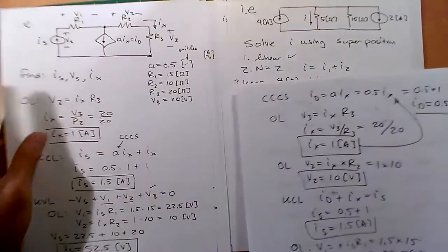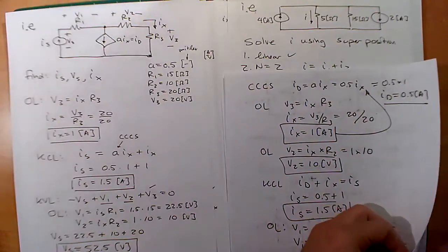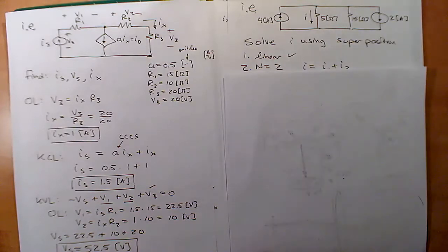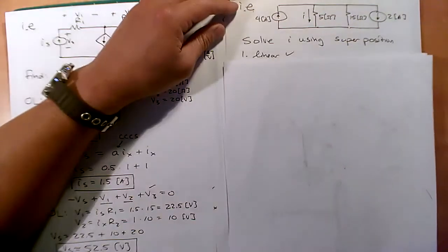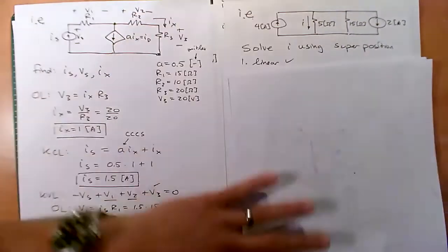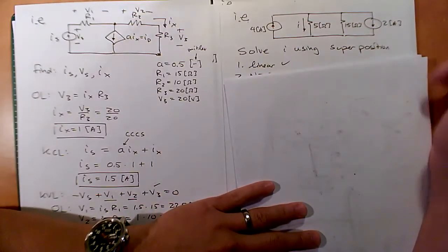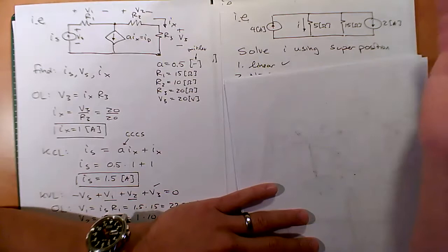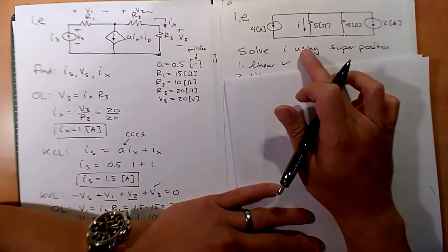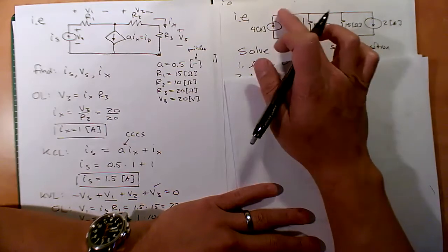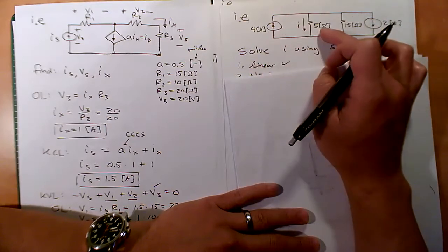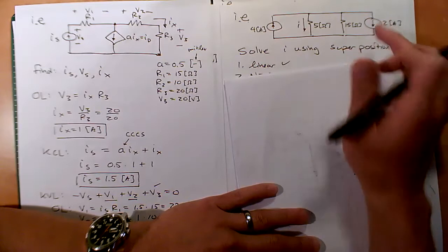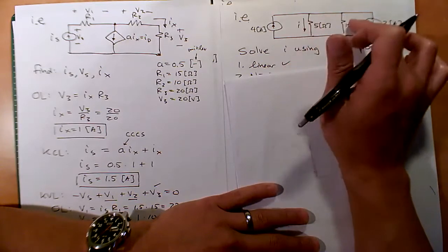Ooh, a superposition problem. Okay. So this is asking to solve for this current using superposition. You could use any, KVL, KCL. Could you use current divider? I think you could use current divider. If you knew the total current going into both of these resistors, which is a little tricky because you have these two, then you could sure enough use current divider.